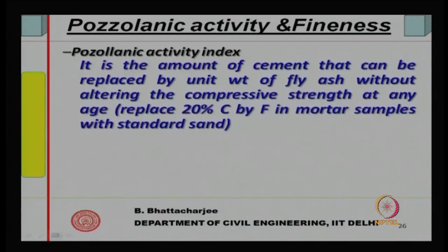Pozzolanic activity index is one of the indices. Like lime reactivity is in a way pozzolanic activity, because we tested cubes and the strength is measured, and that lime reactivity tells us about the strength potential of the pozzolana if you mix it with lime. So, that is in a way some sort of indicator of pozzolanic activity, but pozzolanic activity index is defined in a specific manner.